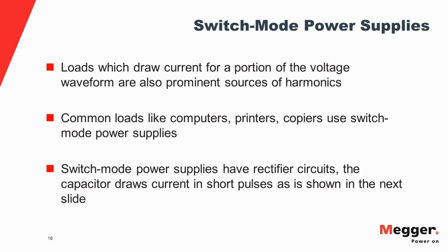Now, because switch mode power supplies have rectifier circuits in them, there is a capacitor on the output side of the rectifier circuit which charges and discharges every cycle, and it draws a short amount of current when it charges, and that corresponds to the peak of the voltage waveform.